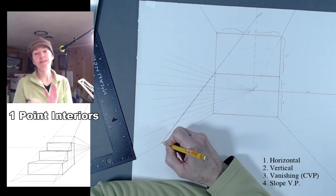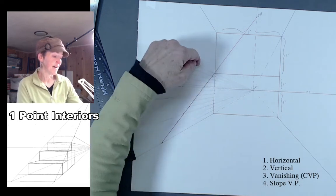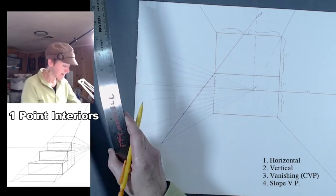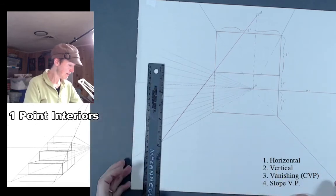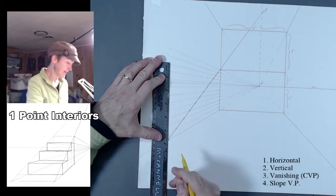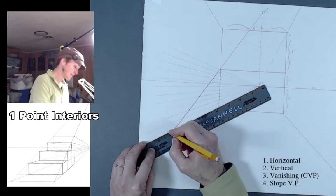And from each of those dots, I want you to draw a vertical line going straight up until it hits the next line, the next vanishing line. So I'll do a couple and then I'll pause the video so that you can pause it as well and get caught up on that step. So I'll do a couple of them just to show what I'm looking for here. So we're going to go straight up, and we've already got that vanishing line drawn, but I'm going to darken it now so that we can really see the profile of the steps starting to develop.